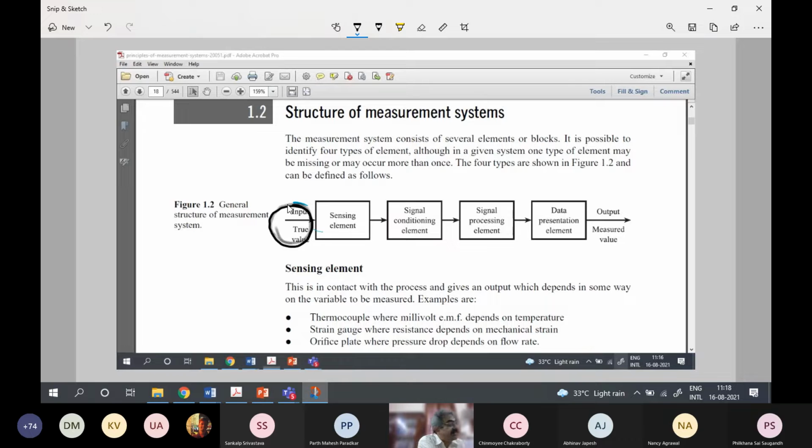So this is, let us say, the furnace. We are trying to measure the temperature in the furnace. We are in an industrial instrumentation course. And there exists some temperature which is its true value. Really, there is some temperature in the furnace. Actually, the temperature in the furnace will be varying, but we are talking about the point where the sensor is. So the furnace wall is there. In the wall, there is what is called a thermowell created, and the temperature sensor is inserted into the thermowell.